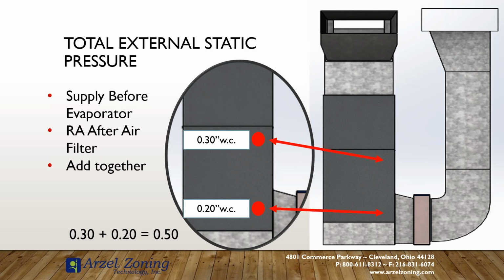So with our system, your motor is able to start against open dampers, ramp up to the higher pressure, and then as your equipment goes to cycle off, the RZL dampers revert back to open, and that allows that motor to ramp back down to a static pressure that's acceptable for it before it shuts off. So we can take that and we can push it higher, and we can give our customers better performance.